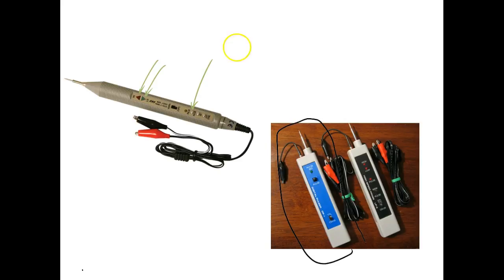Yeah, the problem we have is, we got something like this, and it's sitting there for a high, and then here it pulses low, and the pulse is like for 1 millisecond. Would you be able to see the red light come on that pulse on that probe for 1 millisecond? It comes on, but our eyes don't see it come on. So the pulse indicator here has what we call a one-shot in it.